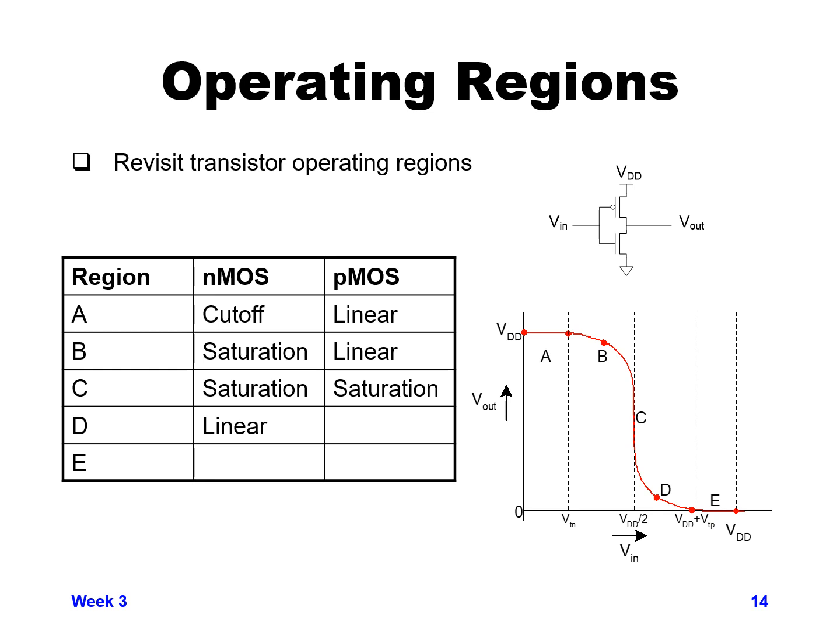And then everything flips when you get into region D. It's kind of flipped from region B, where your NMOS device is now in linear region, your PMOS device is in saturation, and then finally in the last region there, your PMOS device is basically turned off in cutoff region, and your NMOS device is in the linear region, and there's not much current flowing just because your output voltage is so close to VSS that it doesn't have much current going through it anymore.